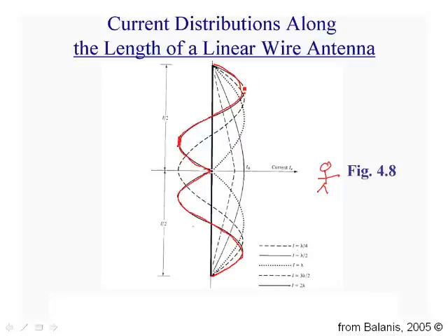So you can see already that this series of maxima will have an impact on where what we call the nulls in the radiation pattern are placed. This antenna will indeed exhibit a null off in the so-called broadside direction. In other words, if you want to call it the XY plane, or in other words, perpendicular to the wire. We'll see how that is played out in the mathematics as we go ahead, though.